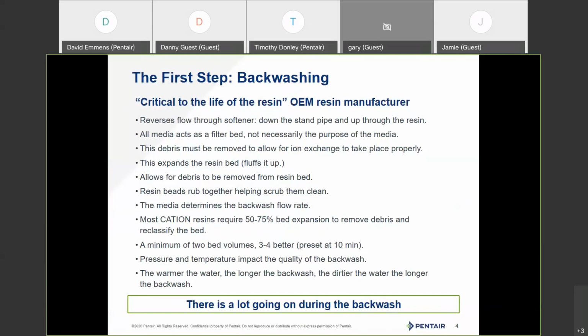It's gonna load up with dirt. And on top of it, if there's any non-polar stuff in there, like other parts of the resin bead, it's gonna attract organics to stick to it. And that's gonna happen in the upper third of the bed, okay?